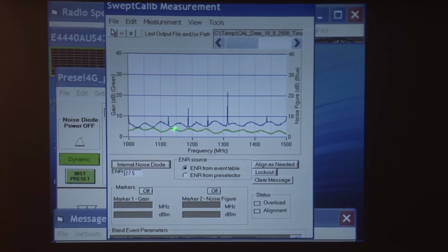Noise figure, on the other hand, is important to know because this tells us how sensitive we are. Now we say, gosh darn it, we put that long line in there, our noise figure went up, this has degraded our ability to see weak signals. So, what are we going to do about that? Well, we'll get an auxiliary preamplifier hooked up, and we'll put the auxiliary preamplifier at the bottom end of the RF line, right at the input to the spectrum analyzer. And I'm going to do that by wiring it in here momentarily.